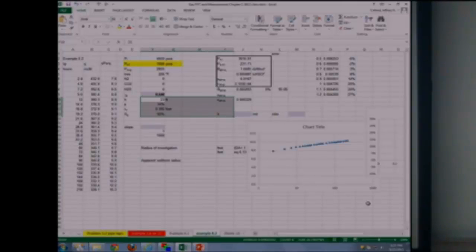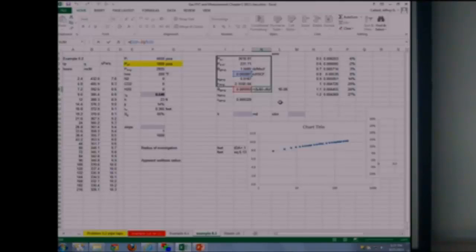Were we given the gas gravity? No, I don't know. You see how accurate that number is? Yeah. We used goal-seek. We actually didn't use goal-seek because goal-seek failed us. We used solver. And we set the tolerance of 10 to the minus 6. And we try to get that number right there, which is the relative error between the B sub G given and the B sub G we would calculate as a function of gas gravity. So we use solver.